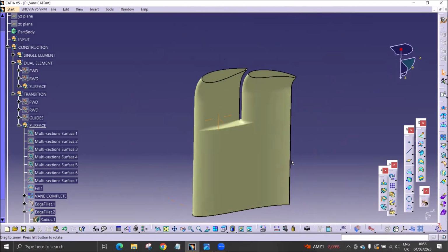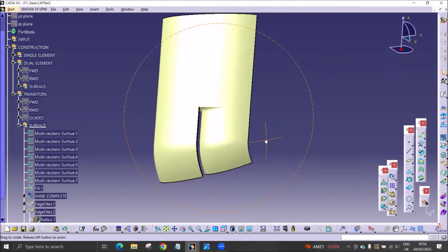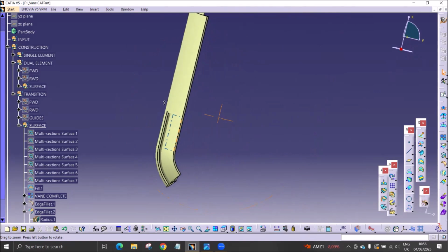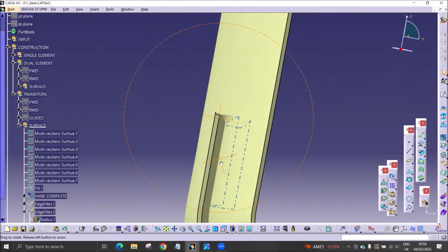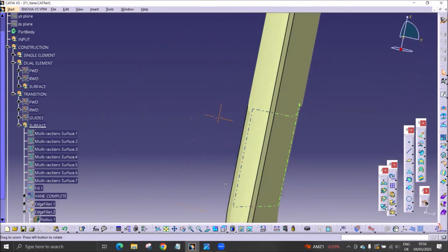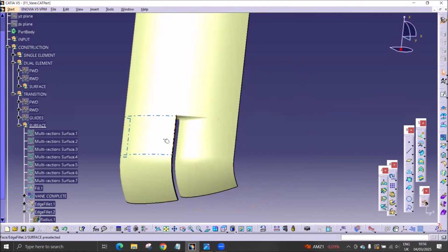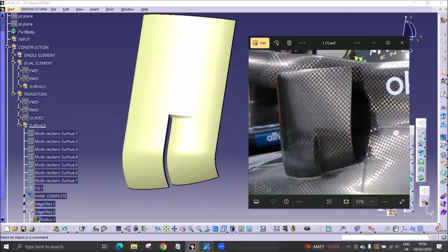part. So you can see how the transition worked between two elements and one element, and you can see that we have a very nice straight surface. There is nothing bumpy about that. There is no dip inside or something. It's a very clean slot gap here. This slot gap won't create a lot of turbulences. Important is just that the slot gap is aligned to the flow in this area, but assuming that this flow is in a straight line, this is pretty okay.